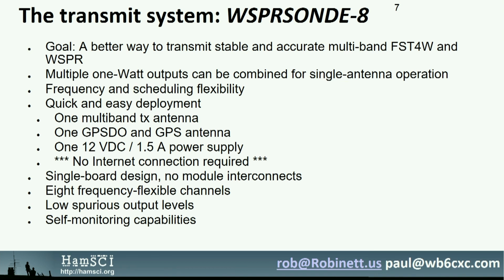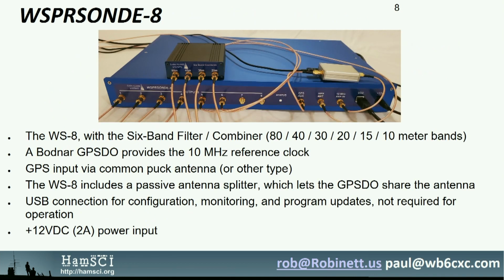Plug in a 12-volt power supply. Actually, anywhere from 9 to 24 volts works, but we use 12 typically. And the antenna. And how do you get from 6 outputs or 8 outputs to 1 antenna? I'll do that on the next slide. So there's a combiner. You plug it in and it runs. So that was the goal, and I think we've achieved it.